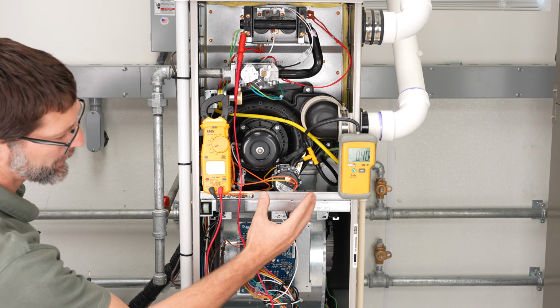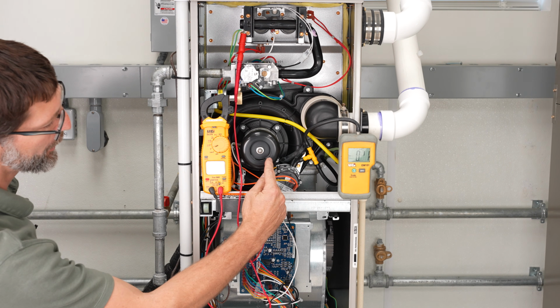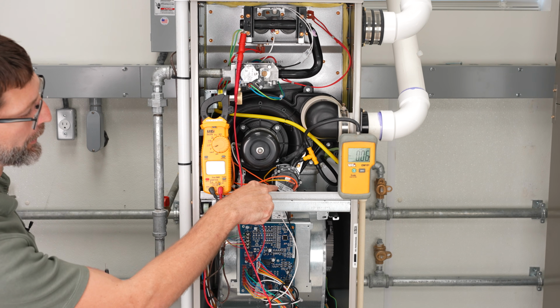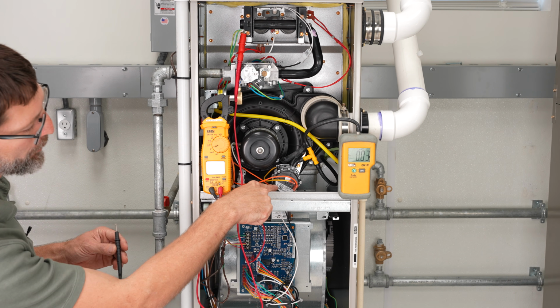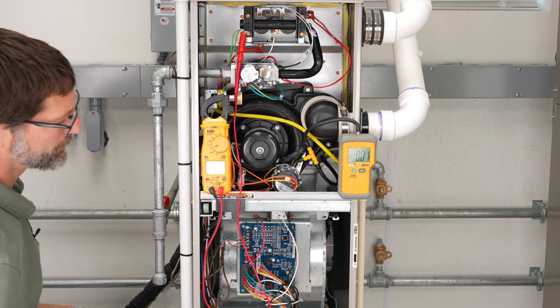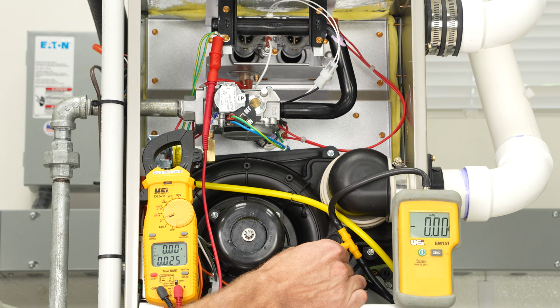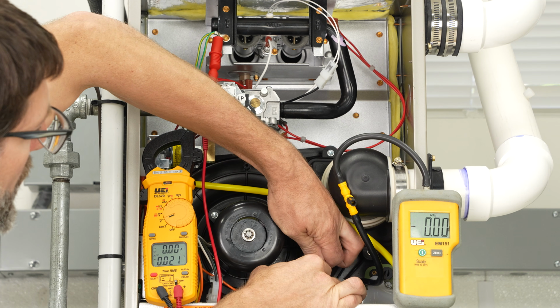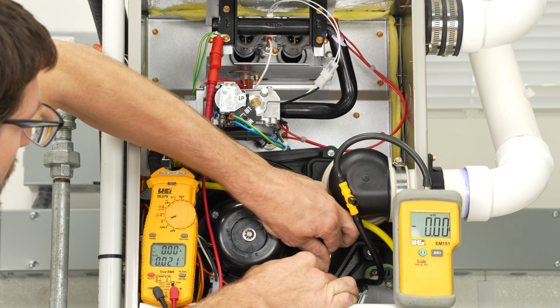So that's how it should be operating. You're going to have a higher pressure applied on the pressure switch than what the rating is. It's usually 2 to sometimes even 3 times as much. So right now, this is all good. Now you can take this right here and switch that with the one in the back. And so you want to make sure to test on both of these.